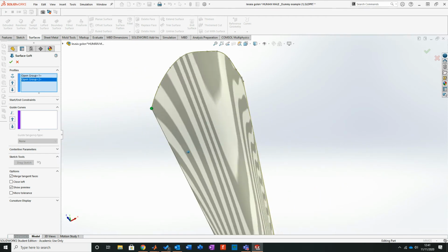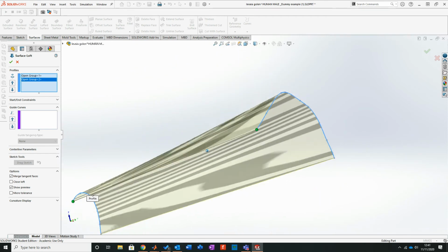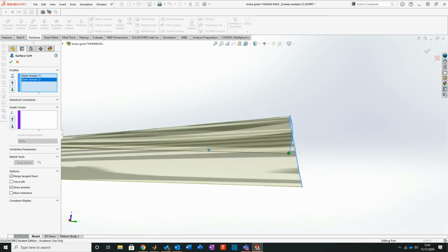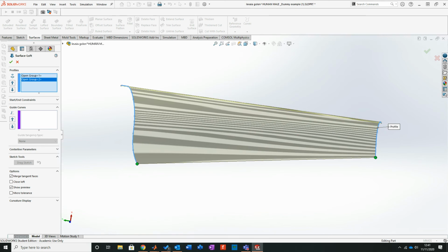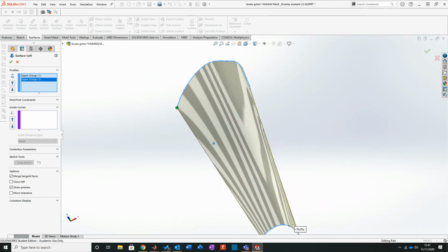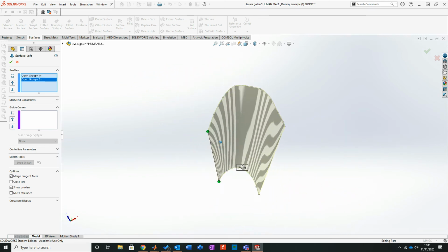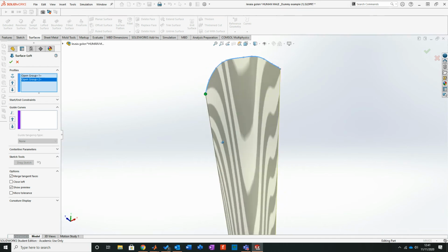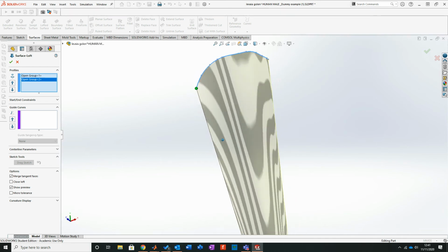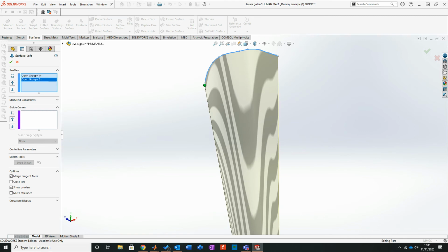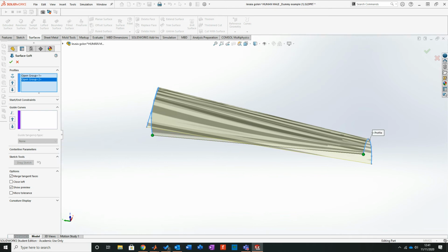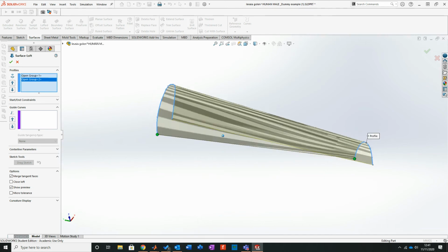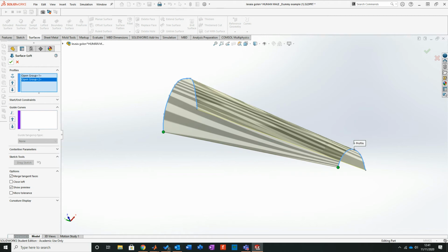As an initial profile, you look at the zebra stripes. They're not nicked, they're not twisted, they're concentric all the way down. That is a good, very good start. I quite like that, because you look at them profiles, you look at the deformations. Here you can see here it goes quite linearized to the front. So if I look there, you'll notice it does go quite linear. So what we really want to do is now try to pop it out, so to speak.